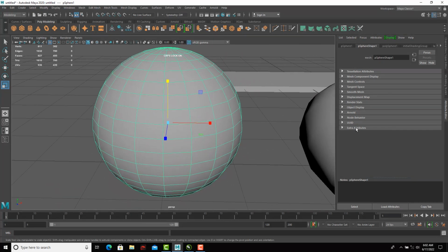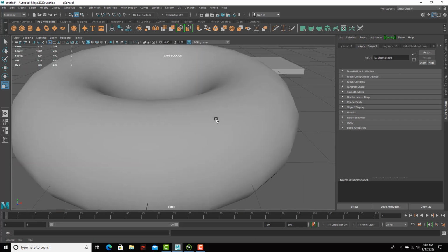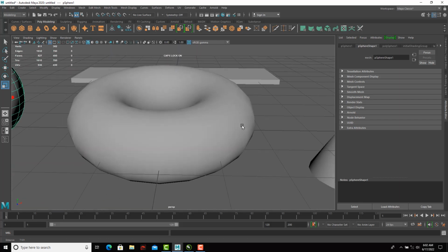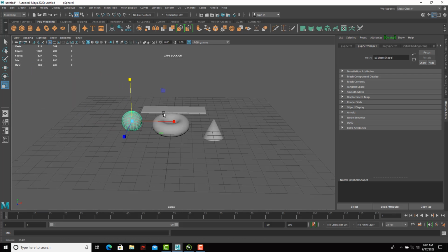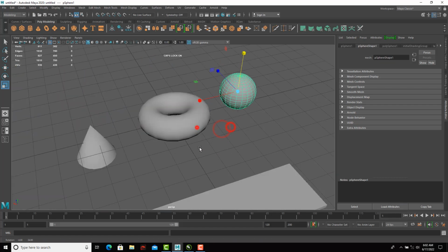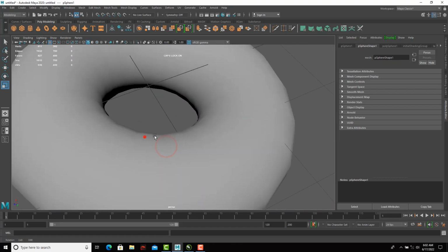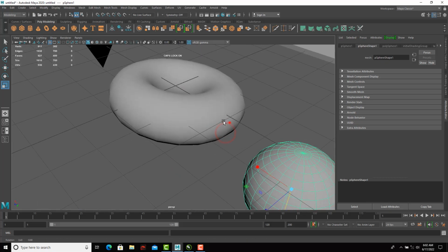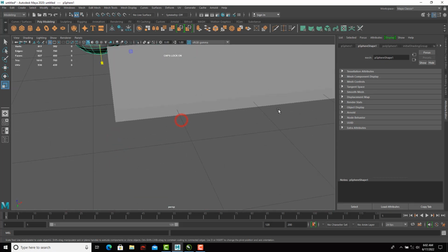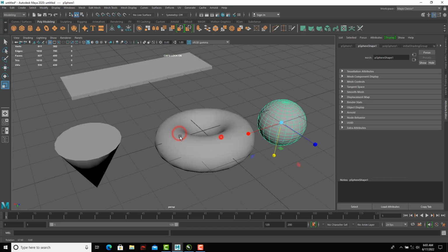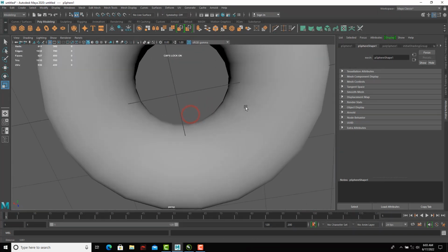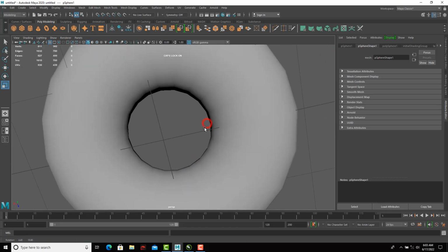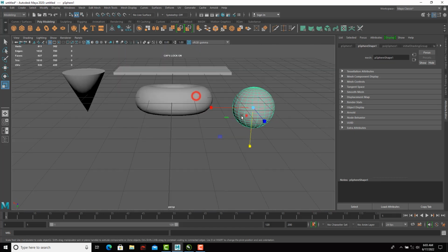And if I still want to bring back the other guy, then I have to what? Drag it. You can see. And if I want to reduce this, then I'll have to switch to zoom by holding down my Alt key, then right click and drag this guy down. So you need to learn how to blend with this. You can see what I'm doing. You need to learn how to navigate like this, like a pro. I can even rotate to the bottom view, you can see what I'm doing.